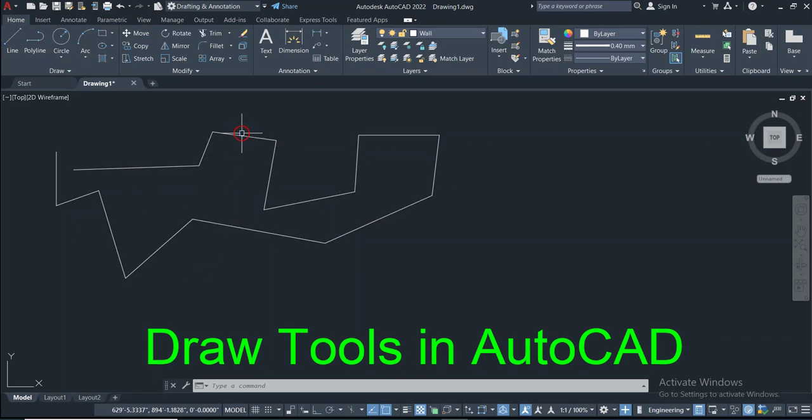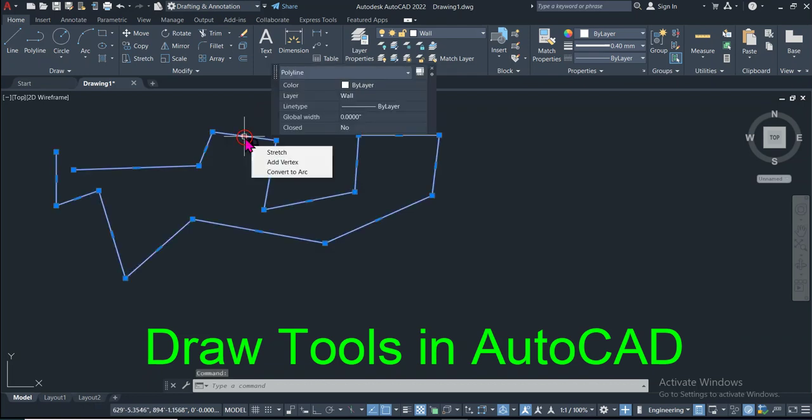If I want to select only this segment, when I click, all the segments in the polyline are selected. So a polyline is a line which is made up of different segments, and all those segments are acting as a single object. So this is the main difference between the line and the polyline.